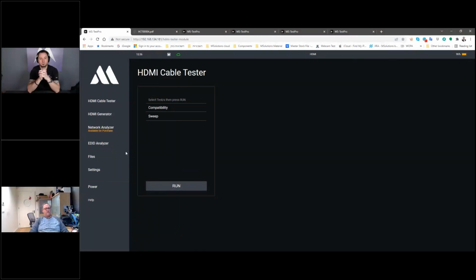If you knew how to test the HDMI cable and to replace it, you don't need to touch the infrastructure of the HDBaseT cables or the LAN cables, because the problem is in a small cable coming from the source to the HDBaseT transmitter, and that's it. Right. It's important to remember. Those are practical comments from things that I have seen. I've seen that a lot of times.